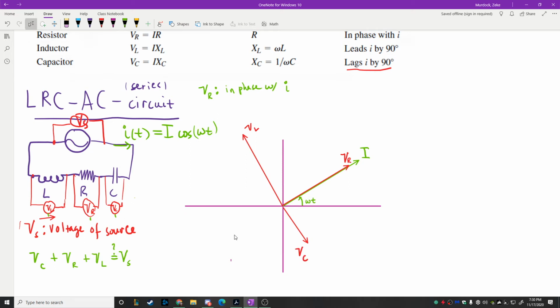And now the idea here would be that all of these phasors basically stay locked just as they are, where these two make right angles here and these two make right angles here, right? I'm going to take those off the diagram, but they stay locked like this and they rotate around in a circle like this. At any moment in time, I can drop a line down like this, and I can figure out exactly what the voltage across the capacitor is going to be.